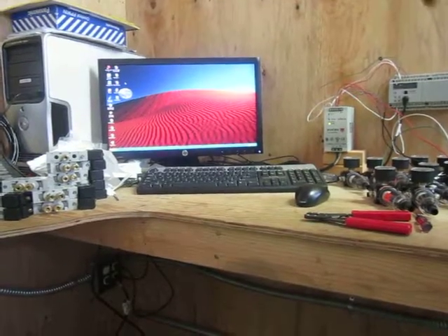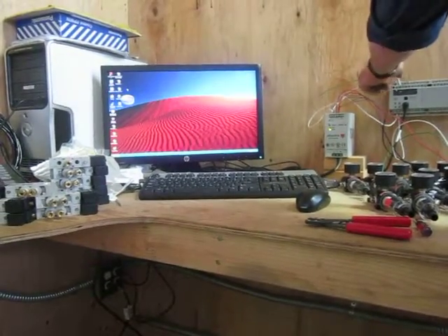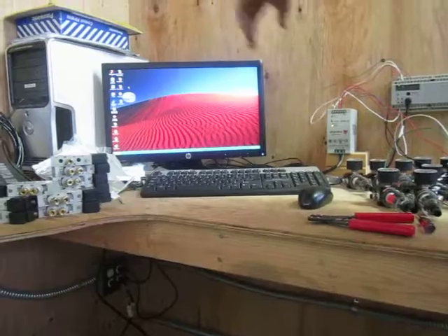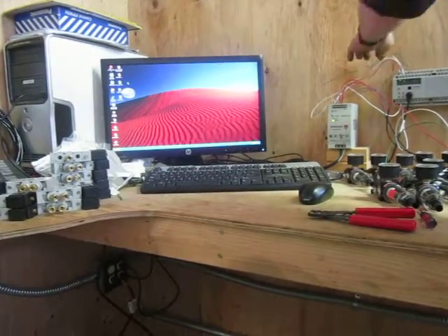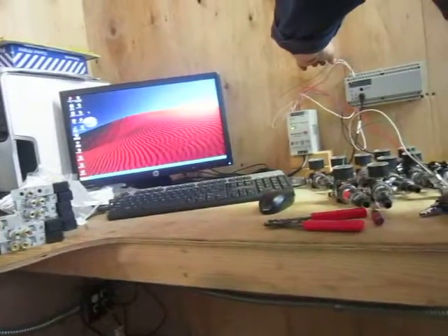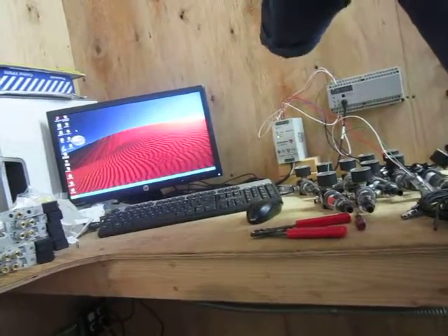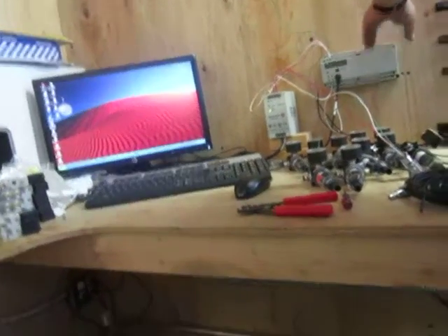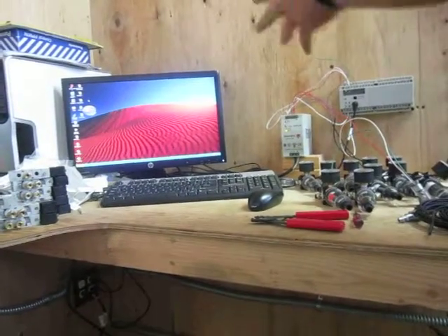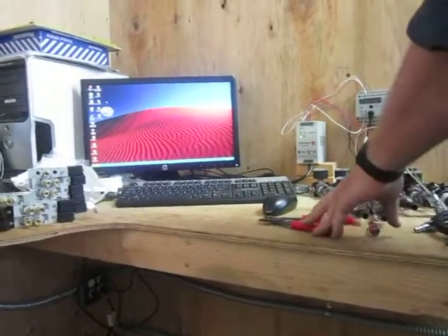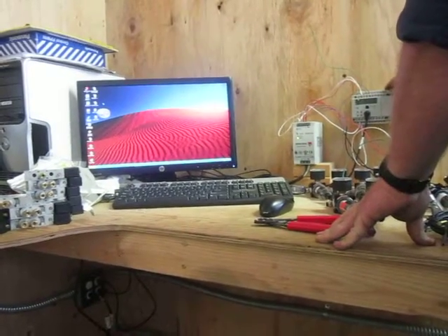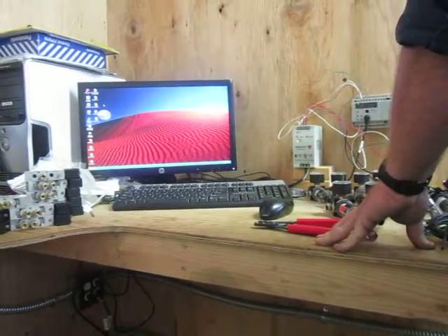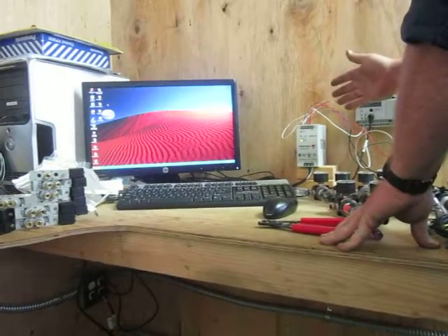I didn't realize you have a power supply that goes, so this is your power supply, this is your PLC. This is the cable that goes to the USB port to program it all. You notice right here, this red, white, and this green, which is not hooked up, this is just a ground wire, so it all goes to common. But these two power supply wires are the main power supply to the PLC. I was thinking that you have the power in and the power out should come out of these terminals. It wasn't true. All these things have to be hooked up directly to the power source.